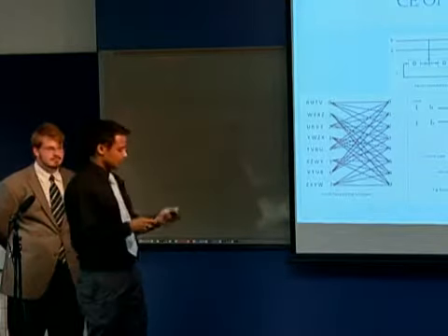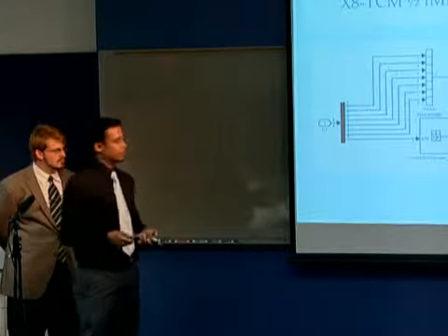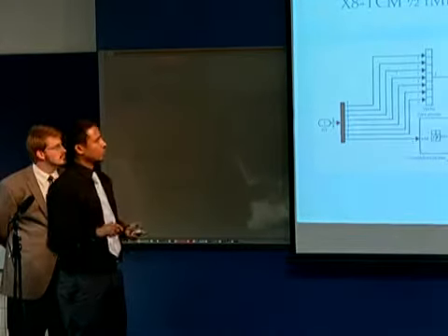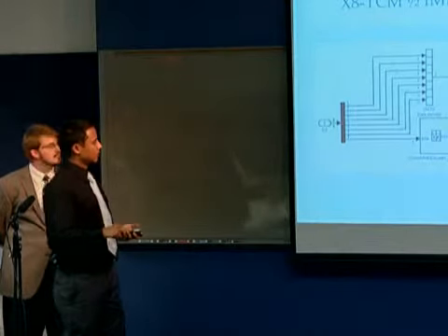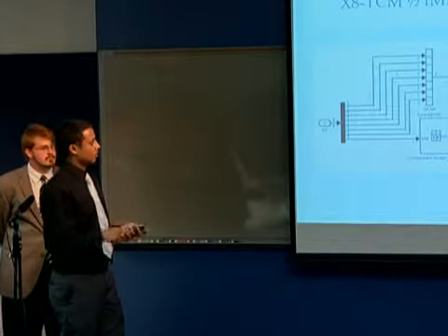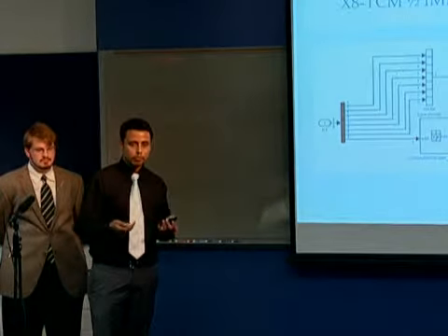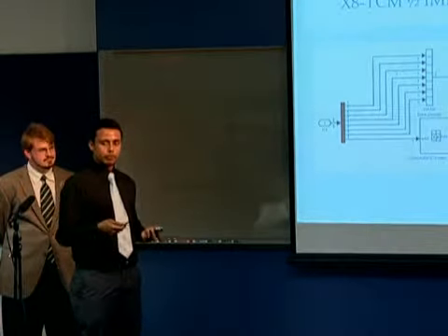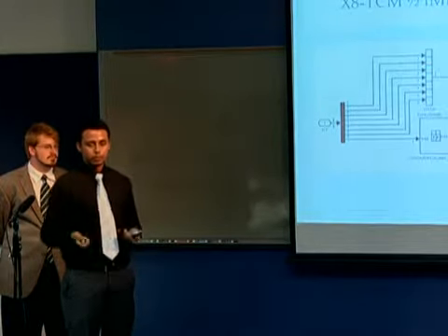It's not clear in there, but this is the trellis-coded modulation implementation in Simulink. So this is the convolution encoder. We used a truth table for the convolution encoder, but previously we used Stateflow for that, and we can also use a built-in Simulink block.